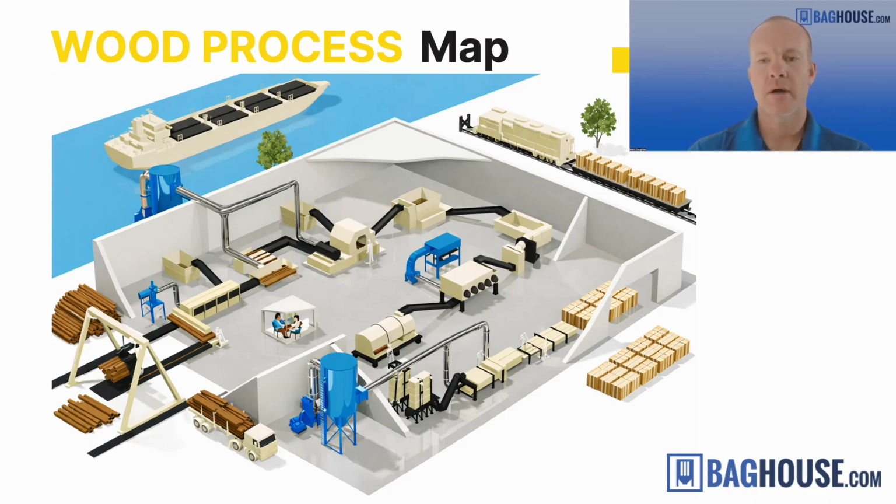And then you have engineered ductwork, which is sized and designed to pull that dust out of your shop and out of that process through the dust collection system using a system fan or blower, and then exhaust clean air either outside of the facility or, and we can talk about this a little more later, potentially recycle it back into your facility to maintain pressure in the building or to help lower your heating and cooling costs. So that's a general wood shop you see there, with pretty typical elements that we'll commonly see.